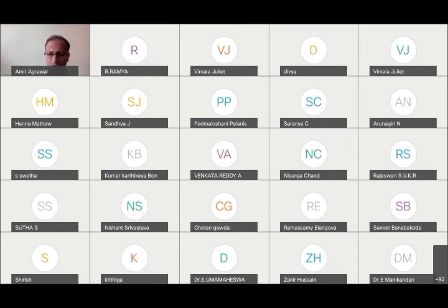So although you can see that two-dimensional hydrodynamic focusing is straightforward, three-dimensional hydrodynamic focusing is not that straightforward. And again, there are some designs in the previous slide, which we did not go through because of paucity of time. But what you would realize is that these are all complex designs with several limitations. The major ones being that either they need several pumps and accessories to have multiple inlets and outlets and so on, or they are complicated to fabricate.